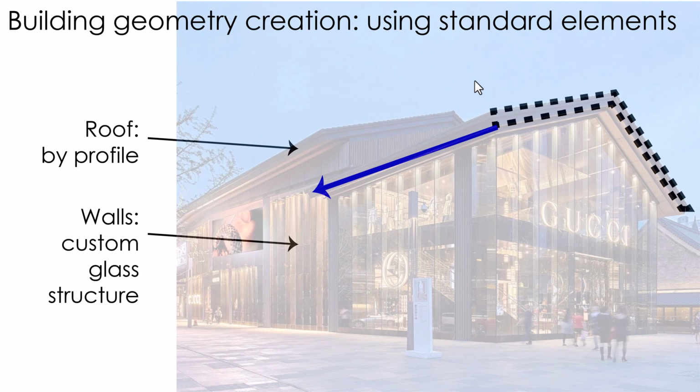And there you go. You just make a solid wall, but make it maybe an inch thick and out of glass, and you've got most of it. The little thin elements you might create using other walls going perpendicular, but they will join. Revit will join them, and you'll end up with nice lines on the front.